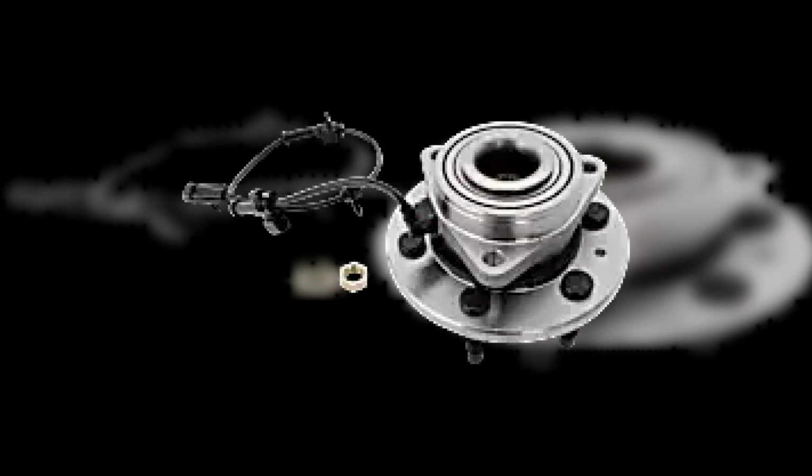3. Check electrical connections, and make sure the wheel speed sensors' electrical connections are secure. Look for damaged wires, loose connections, or corrosion. 4. Test the wheel speed sensor. Use a multimeter to measure the resistance of the wheel speed sensor. Consult the manufacturer's specifications to ensure that the resistance is within the appropriate range.